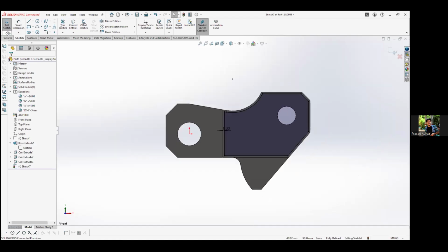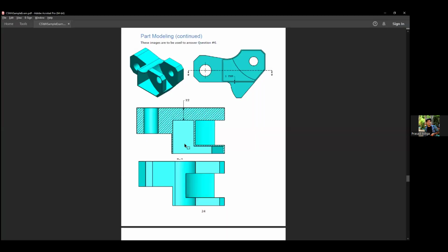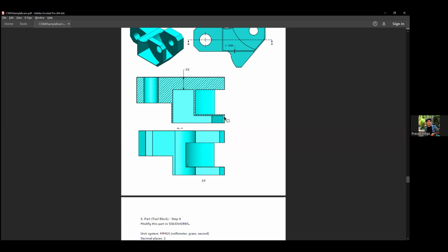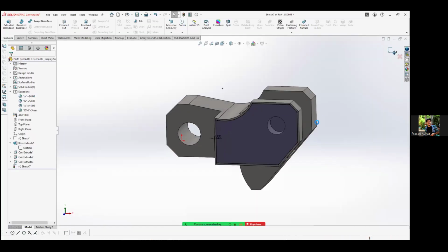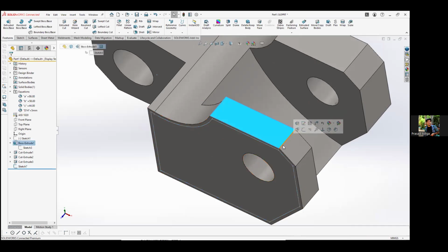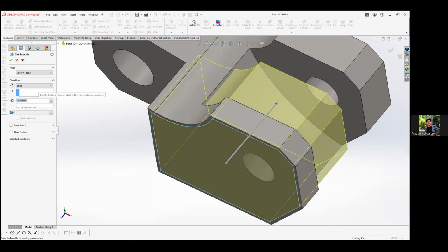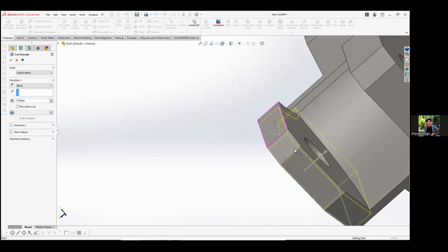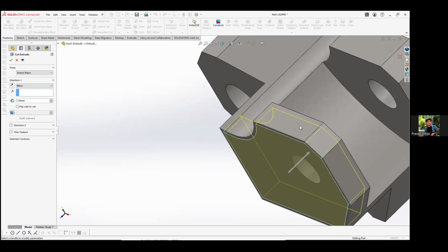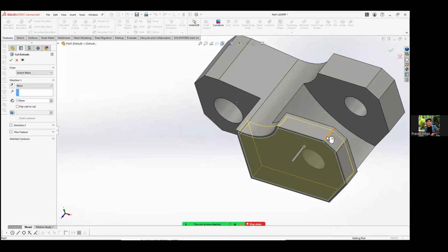So now all you need to do is make sure this offset is ending before 1 mm. Before we go to the extrusion, the length of this particular edge is 8 mm. So we need to cut it for 7 mm only, right? So select the sketch, click on the extrude. Instead of through all, go to blind, put 7. If you don't know how to measure this, you can give an offset afterwards, but that's a risky thing. So what you should do is measure this particular line.